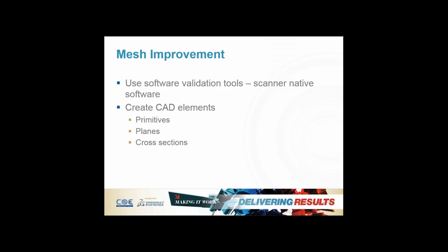More advanced software packages offer a way of creating CAD elements on the 3D scan data and exporting those elements directly to CAD via IGES or STEP. Others can create NURB surfaces on the 3D scan data that can be exported via IGES into CAD. This NURB surface data can be used as a roadmap in CAD when recreating a part.